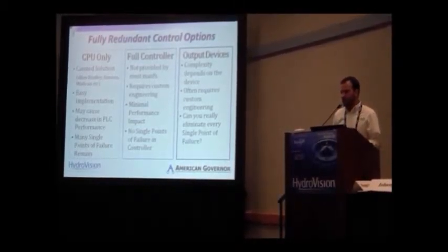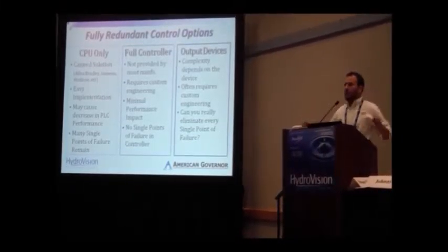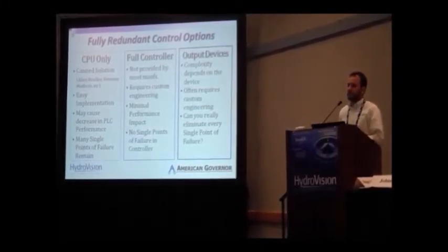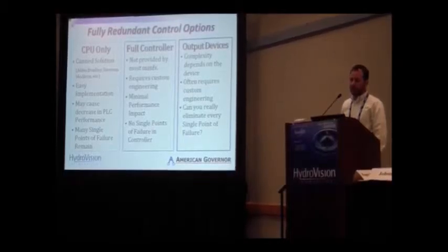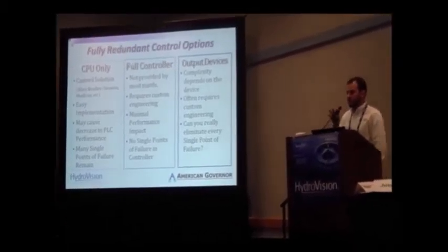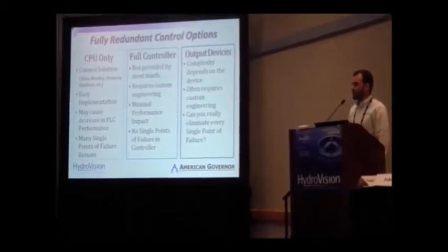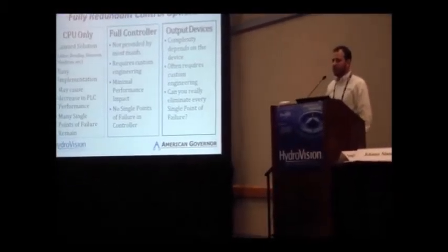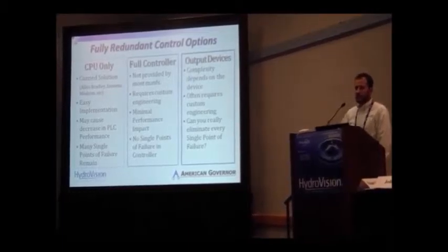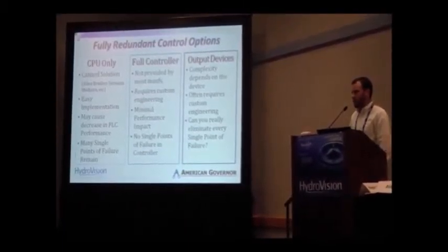There are some downsides that need to be considered, though. These systems are not really designed for single system controllers. They're more designed for a master control unit running, say, 5 bottling lines in a bottling plant. So they're not designed for a single system, a single exciter, a single governor, a single unit controller. There is some decreased PLC performance in the overhead. They're not designed for speed optimization. And you still have many single points of failure. One I/O module is still going to take your unit out. So while you're replacing your CPU, it's just one component.